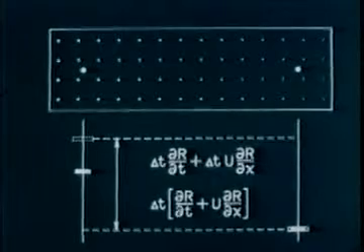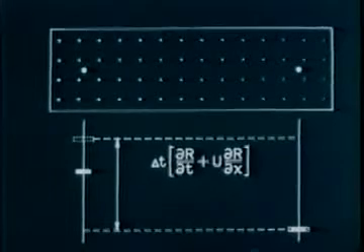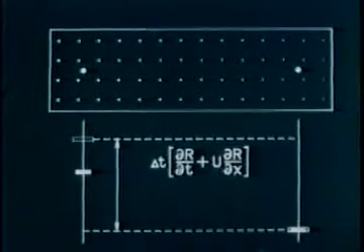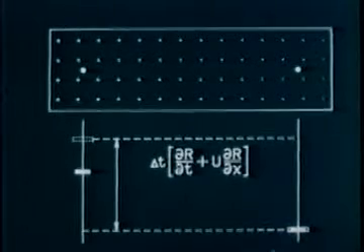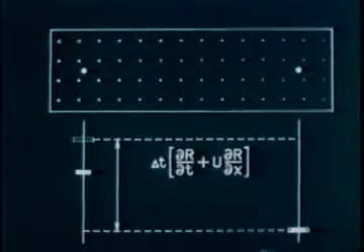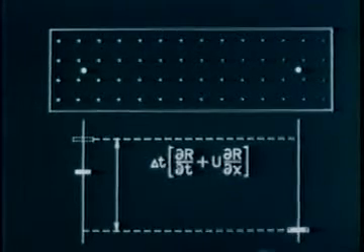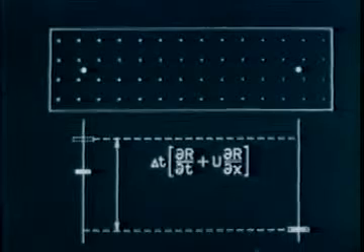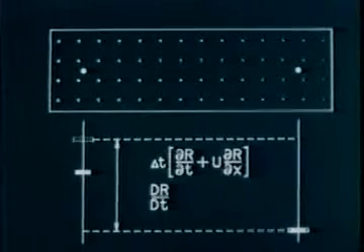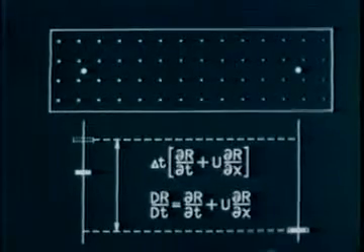The material or substantial derivative is the name given to the expression multiplying the time difference. This is simply the rate of change with respect to time seen by the material point as it passes the laboratory point, expressed in laboratory coordinates. It is important to emphasize that the material derivative is the rate of change seen by a material point as it passes a laboratory point, but expressed in laboratory coordinates. In vector notation, the velocity times the gradient in its direction can be written as the scalar product of velocity and the gradient.